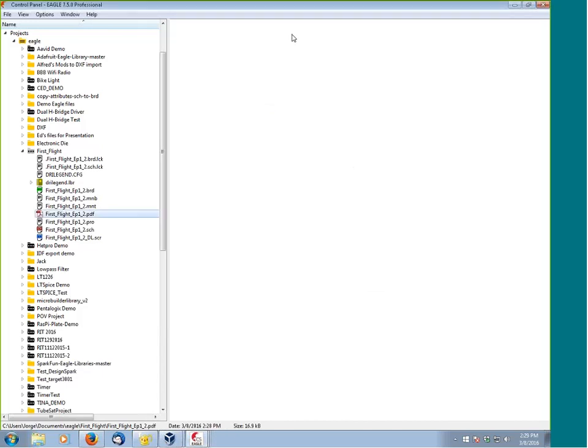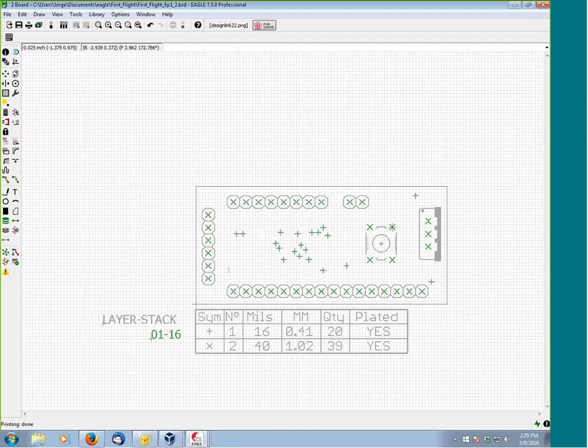Okay, it can also be put in the Gerber, and it can be put in an image. A lot of times, it's going to be very dependent on the board house. Every board house kind of wants it in a different way. So they'll let you know how they want this information presented to you. But this is how you can create the drill legend table. Okay, let's put our layers back the way they were.